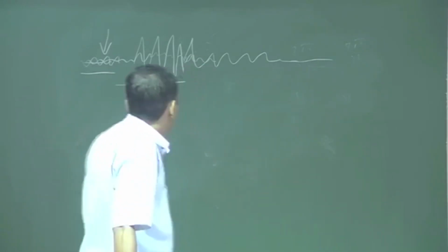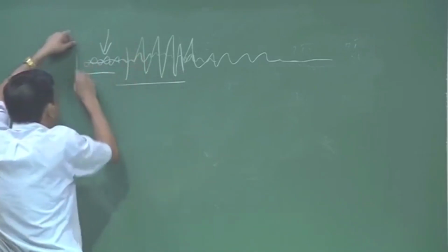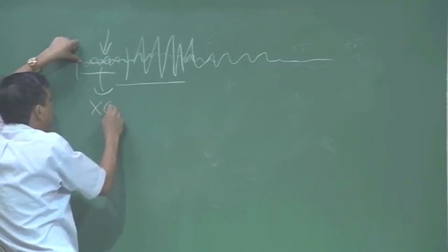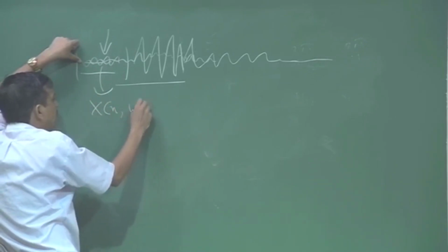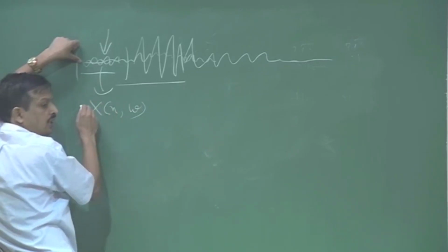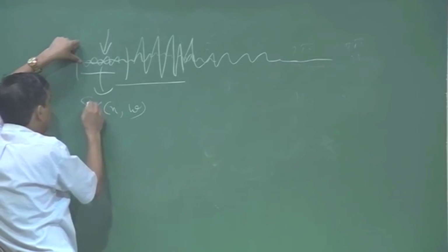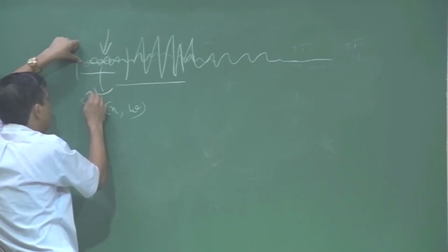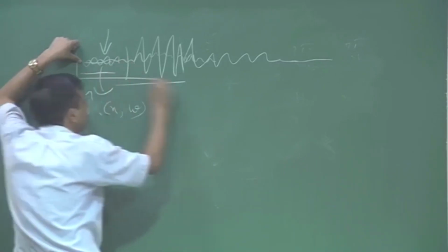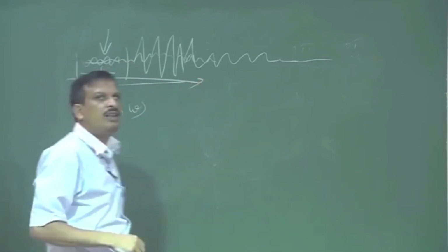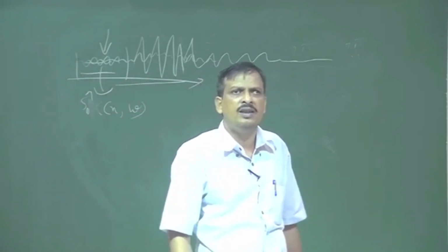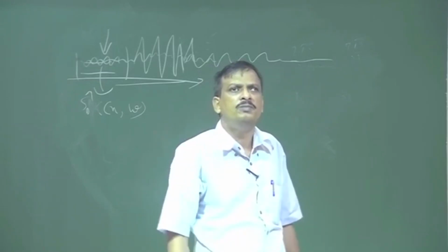So what I will do, I first estimate the noise power by analyzing this portion, take a single window on this portion, and I can estimate that N(ω). Then I apply that noise estimation. So SB is the noise estimation. I can subtract the noise estimation from the signal spectral estimation, and I resynthesize it, I can get back the signal, the noise is removed.